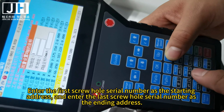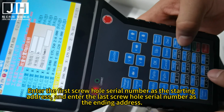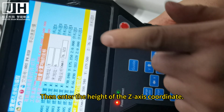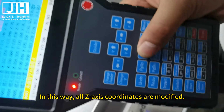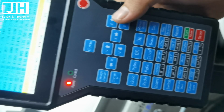Enter the first screw hole serial number as the starting address and enter the last screw hole serial number as the ending address. Then enter the height of the Z-axis coordinate. In this way, all Z-axis coordinates are modified. Z-axis batch modification.